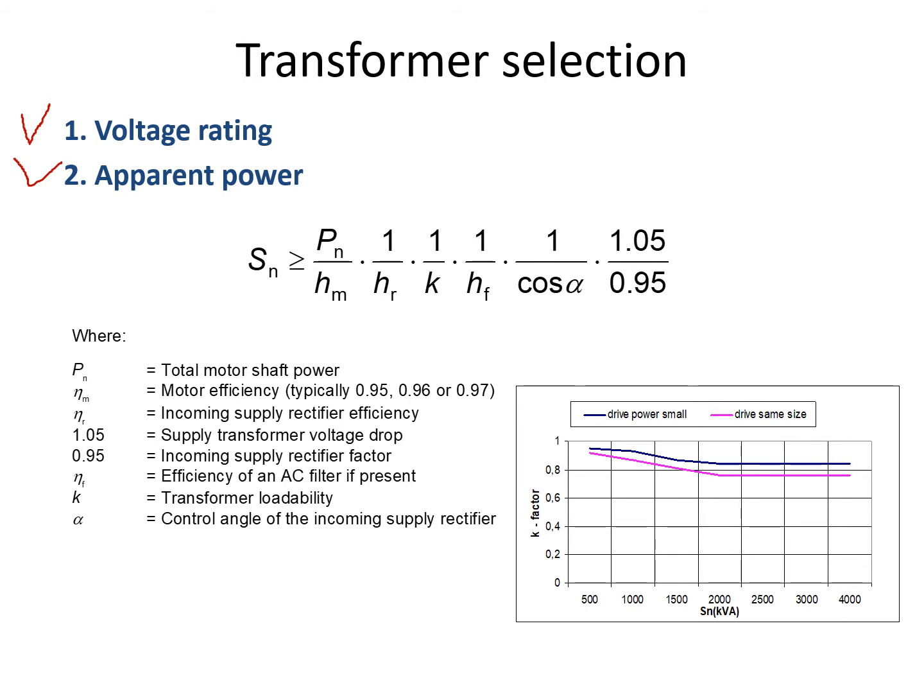So of course we start with motor shaft power here, so you find it in this formula, and then the apparent power of the transformer should be higher than this motor power with the range or the set of coefficients, a description of which you find here. And again I recommend you go and read books from ABB or Danfoss on this topic, so they explain it very well.